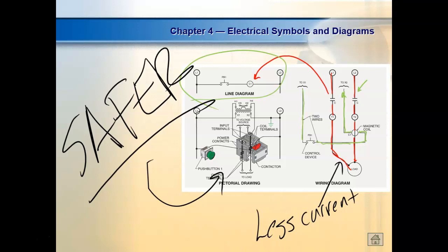And as soon as it does that, if one strand comes out from under that screw, then you change the gauge of the wire. So with stranded wire, we usually have to put on terminals, crimp terminals, or we have to put them in compression screws where we have a trough we put them in and don't let the strands do what? Separate. What advantage is stranded wire?